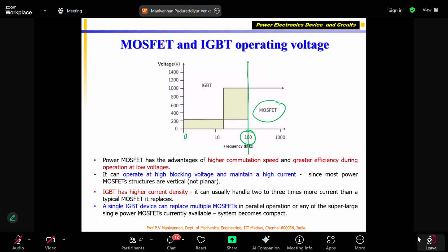So for the motors, correct, we talked about the BLDC motor, the permanent magnet synchronous motor, or the induction motor used in electric vehicles. The operating frequency will be on the order of kilohertz only, generally always lesser than 100 kilohertz. This is how the MOSFETs are designed for operation. You can see that the IGBT can work at lower frequency only, up to 20 or 30 kilohertz, and very rarely up to 50 kilohertz.